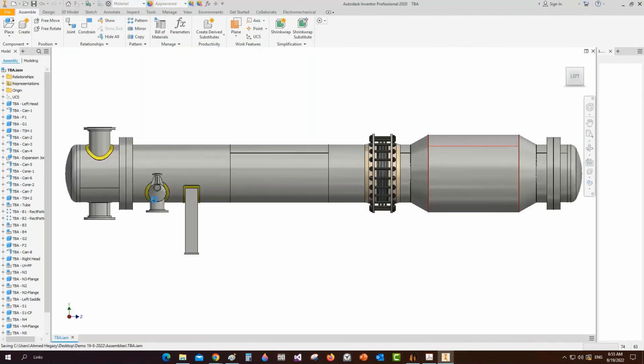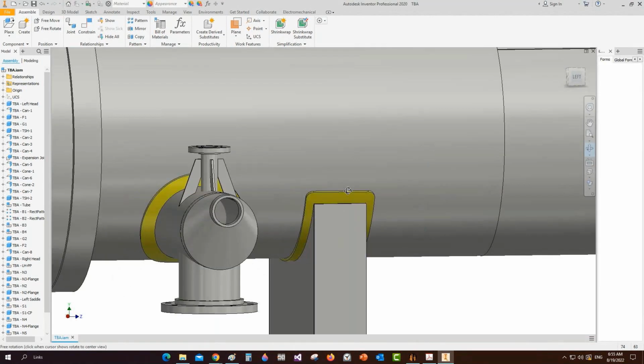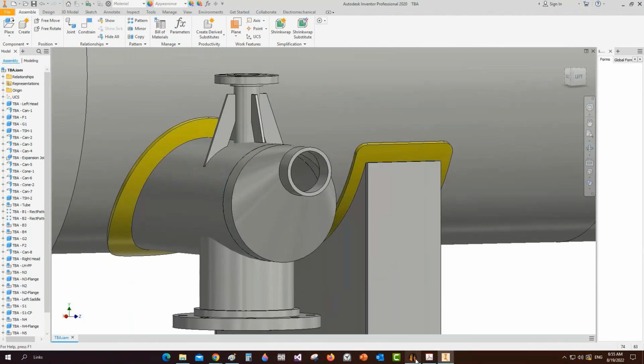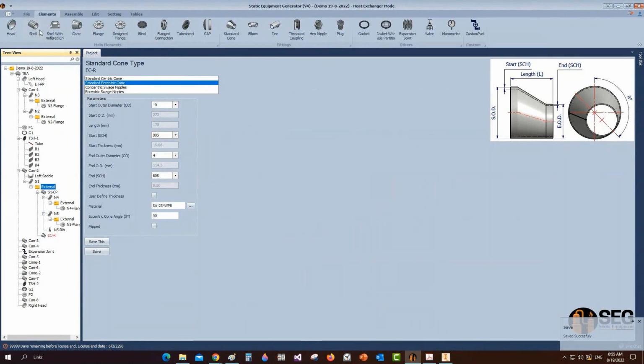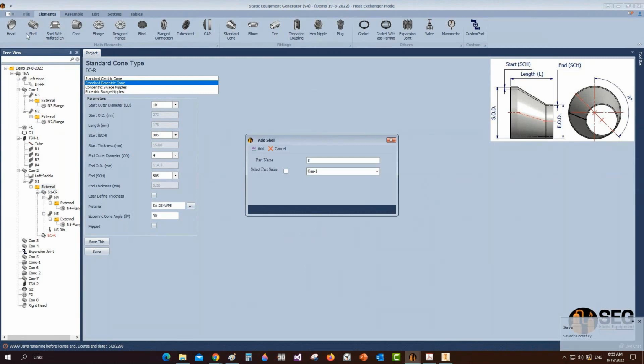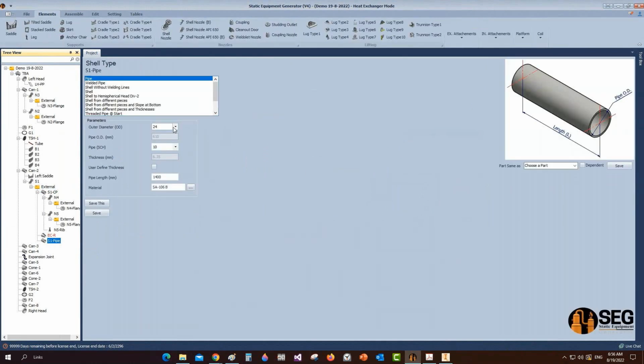Okay, as you can see, it's become on the top, so we need to change it with 180 degree, so this value will be 90 degree. And let's add another element after it, which is another pipe. So this one pipe, let's add another pipe to this one, and this pipe will be the same pipe diameter, which is 4 inches and 80 is scalable, and the length will be 82.